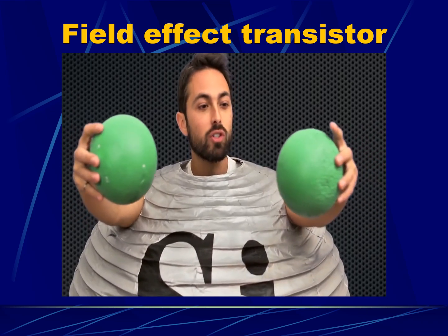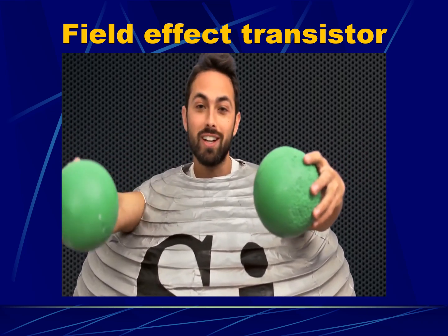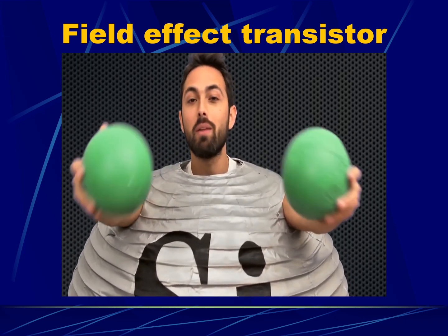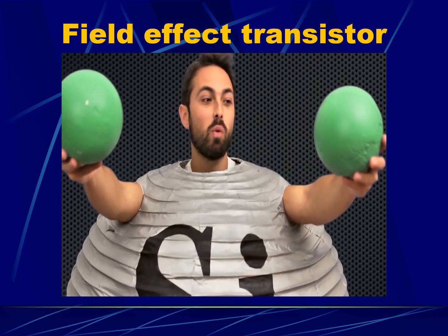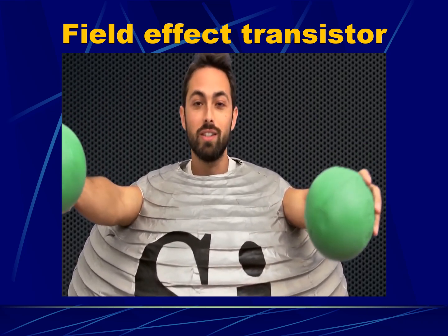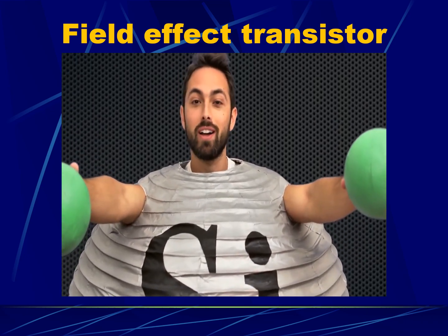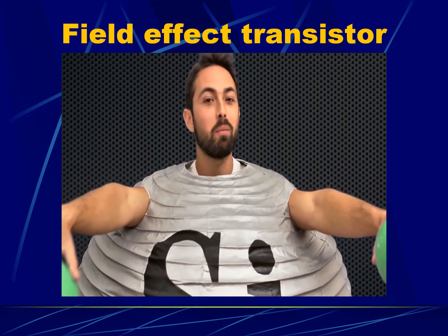As those terminals get closer and closer together, quantum effects become important, and electrons can actually tunnel from one side to the other. So you may not be able to make a barrier high enough to stop them from flowing. Now, this will be a real problem for the future of transistors, but we'll probably only face that another 10 years down the track. So until then, transistors, the way we know them, are going to keep getting better.